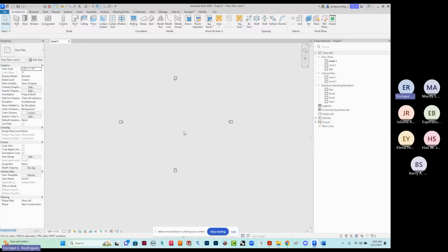And that's what we're going to call, like we did in the northern home, our main elevation. You can leave the name level 1 if you want at this point. If you wanted to change that to floor 1 or main level, you can do that too. But for now, I'm going to leave it as level 1.